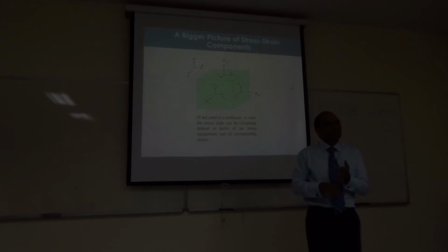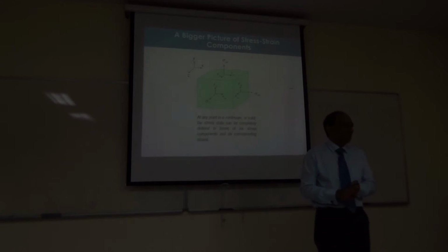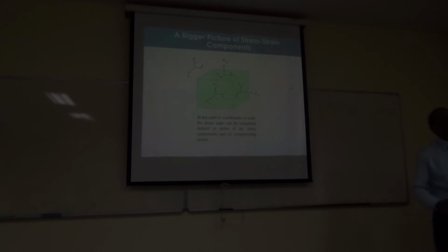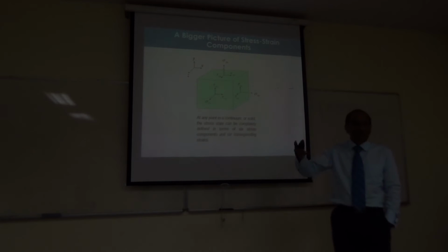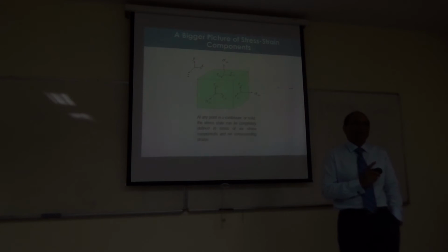One is modulus of elasticity for each direction, E in each direction, and then G for each direction of shear, plus Poisson's ratio, also in each direction. So you need a lot of properties now for this small material block. In fact, 36 in all, 6 by 6, right? So it's not as simple as we started. This is only one problem, that we are not dealing with one stress and one strain component, we are dealing with many. So there is interaction. The whole definition cannot be defined by one number. Many properties are needed just for that purpose. But this is only the beginning of the story.